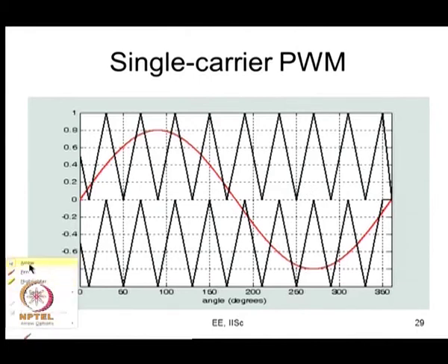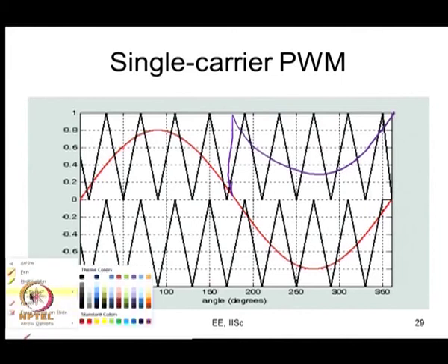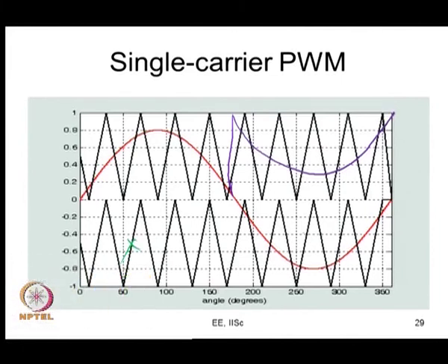So, what you can actually do is, let us say you shift this fellow up. The R phase I have just shifted up. So, the R phase signal is like this. Now, I can actually compare. So, this should be at 0 crossing. So, what I can do is I can ignore totally the lower part, I can ignore this part, I can ignore this part. I can have a level shifted thing which is like this, and this part the sign is level shifted, and you can see that the instance of comparisons all will not change if I do it properly. I have not drawn it very clearly.